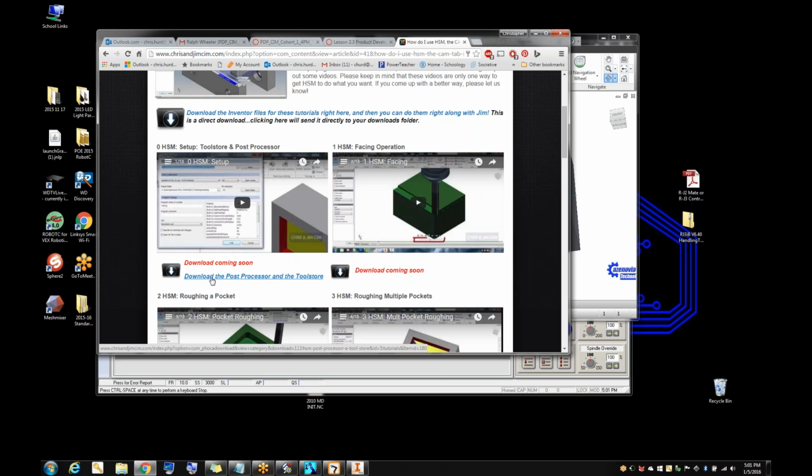All of my rest of my machines are manual changes, and that's just a pain. So the majority of my students, I make them design their container around a 1/2-inch end mill. When we get to the lid, I allow them to use a 3/8 ball and then an engraver. But for the majority of hogging out the base and the bottom of the lid and doing all the outside contours, we do it as quick and dirty and as fast as we can with a 1/2-inch hog.